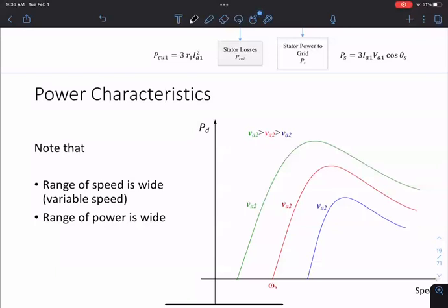And so by changing the voltage, you get to shift this curve this way. For the smaller voltage, the more the curve shifts this way. So you have a pretty wide range of operations by changing voltage here. And while changing the operating characteristics, this is more efficient. Again, you're not changing a resistance, you're changing the voltage.